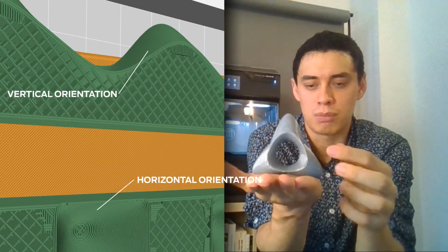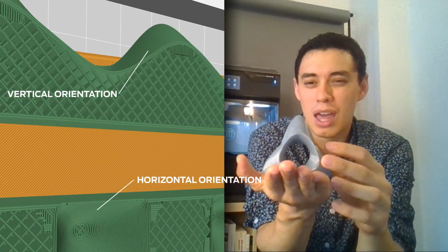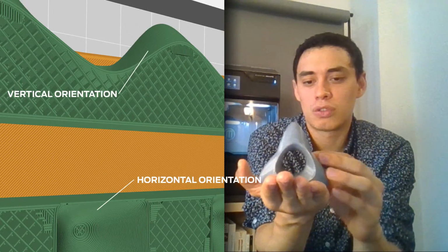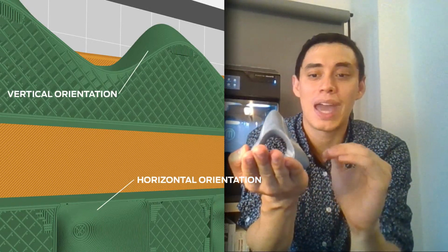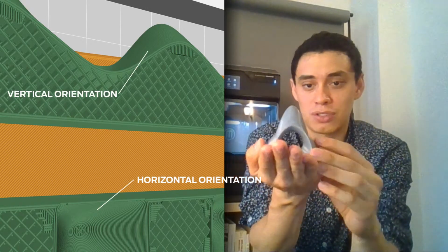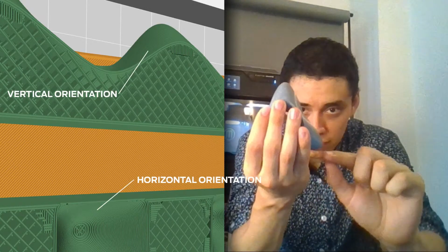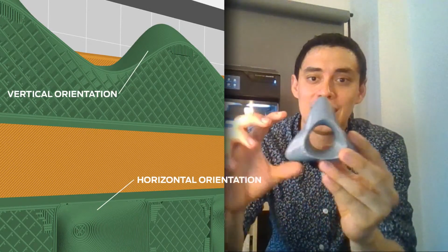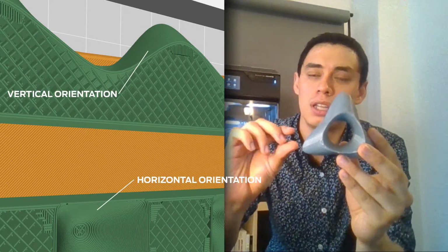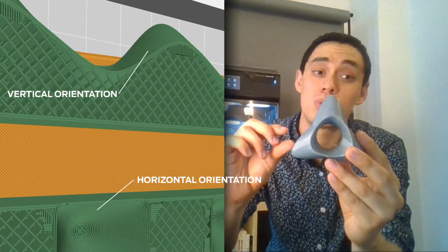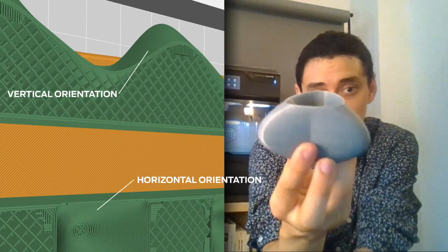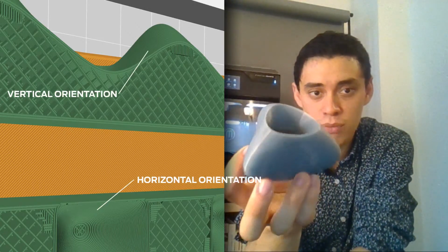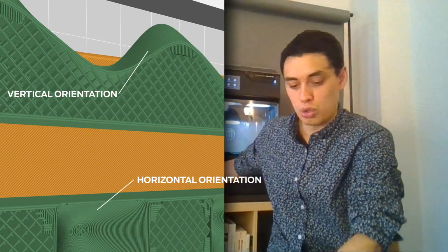Maybe I would have generated more support material. But beyond the amount of support material, what you have to keep in mind is that I would have much less resolution, because I'm trying to cover all of these very dramatic changes in very few steps of the layer count. So just by changing the orientation, I'm able to add so much more detail to my parts.